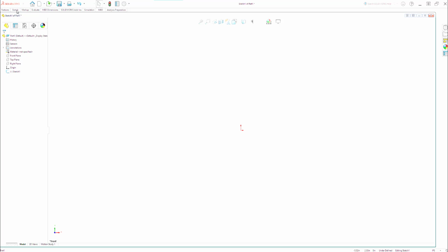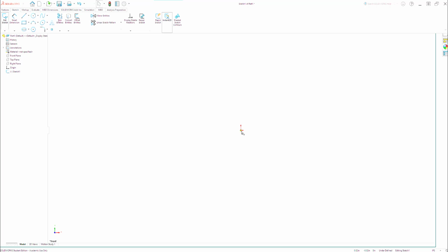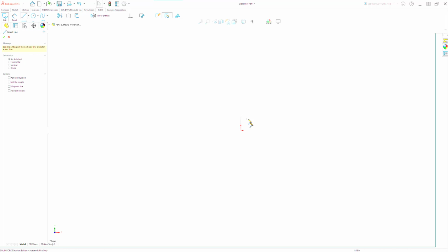So with that, we'll begin our sketch. And our sketch is going to begin on that 0, 0, 0 location. But we have to select something to sketch. Now there's a couple of ways that we can create this particular shape. What I'm going to do is we're going to begin with the line command, and we'll pick the line command, and we'll start the line command. And how do we select things? We left mouse click and release. When we right mouse click, it's typically going to bring up options on the screen. So these are all left mouse clicks that I do to start and stop the line.